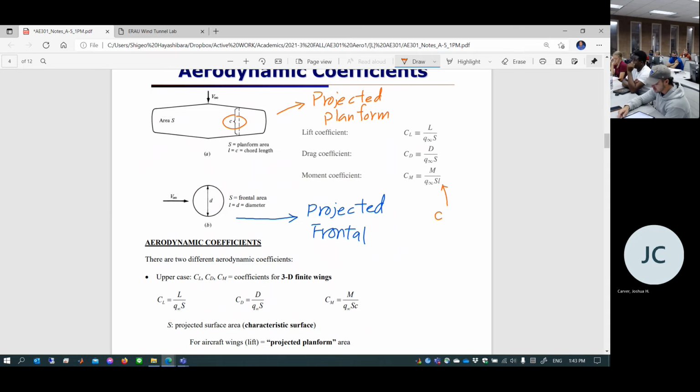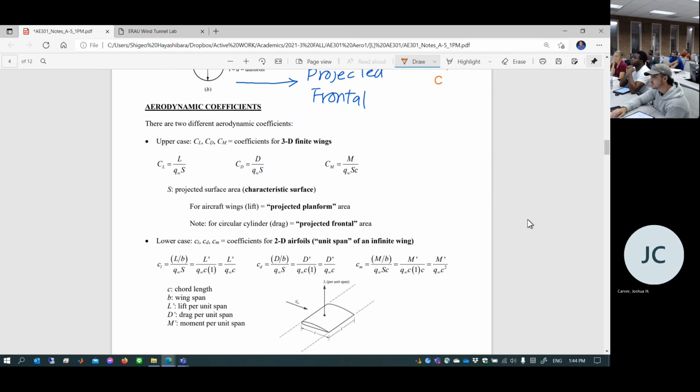So if somebody's designing, I don't know, a concrete brick with aerodynamic drag, I've never heard of it, but if that kind of study is ongoing, that community uses this characteristic length you have to follow through. That's exactly what we're doing. In airplane design, of course, people use chord lengths and then frontal projected area for everything. So we have to be consistent within that community.